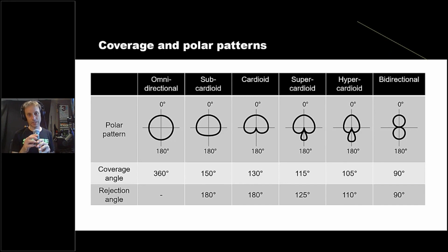But something of interest, the supercardioid pattern, is you'll note that instead of having its angle of greatest rejection being 180 degrees behind the microphone, there's sort of two lobes that are right at some slight angles off from the back. So you can hear there's actually a little bit of pickup right at the back of the microphone there. It's kind of dark sounding. You don't get a lot of highs because the body or the grill of the mic, the structure of it, blocks the high frequencies, but you can still hear me back here because of that little area of pickup. But again, the null right about there. So again, you got a little bit of a different pattern you need to consider there.